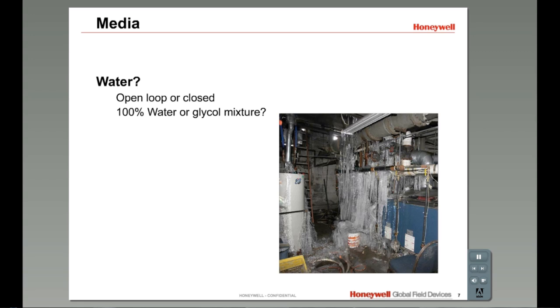For this reason, water used in heating and cooling systems may be mixed with glycol in order to reduce the freezing point. Up to 50% glycol is common. It is important to verify that the components you choose are compatible with glycol if it is used.